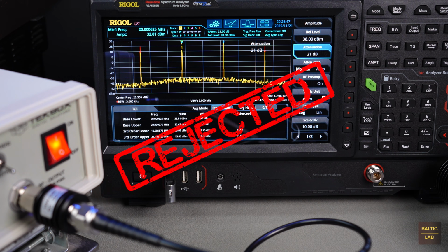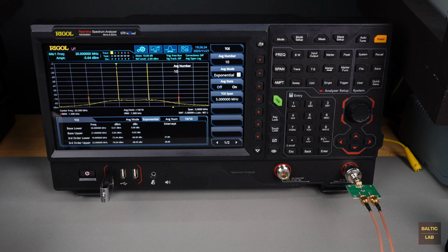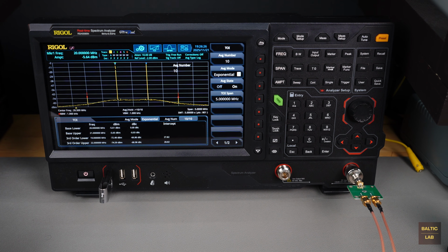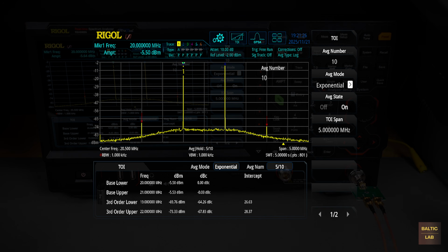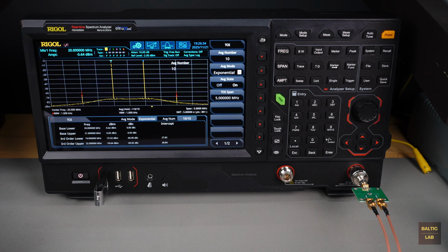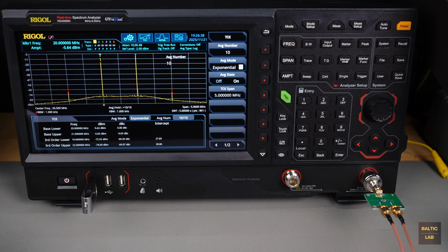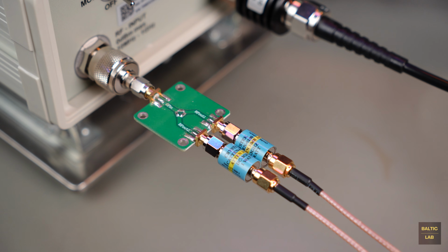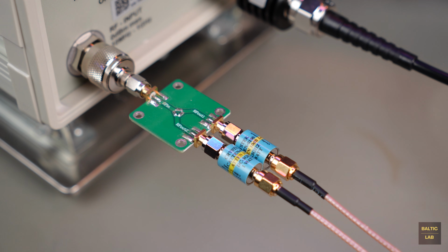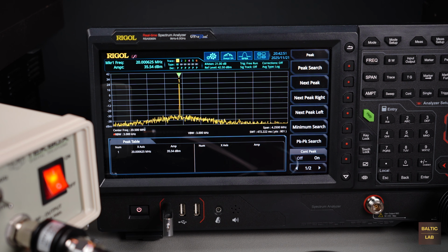This is also expected. The combined tones themselves already have a TOI of around 27 dBm. Through a perfectly linear amplifier with 40 dB gain, this would scale to about 67 dBm, far above the amplifier's expected TOI and therefore irrelevant. Nonetheless, the attenuators remain in place as good practice. The real issue lies elsewhere.